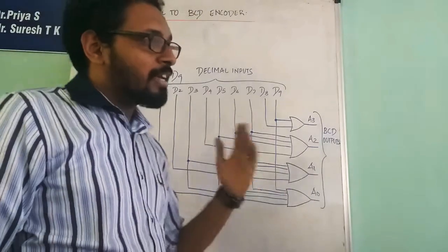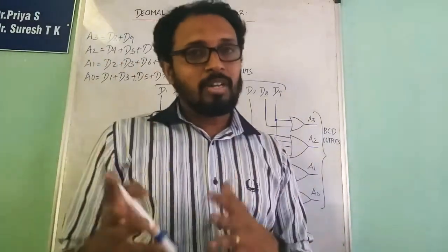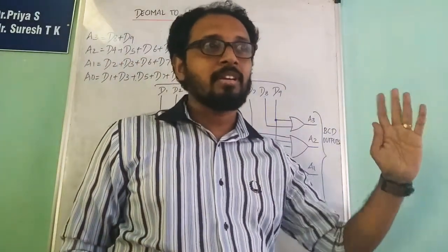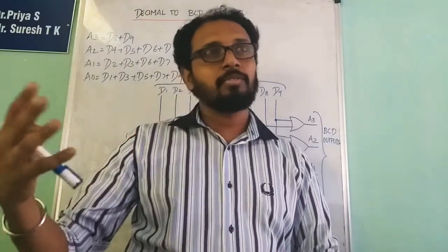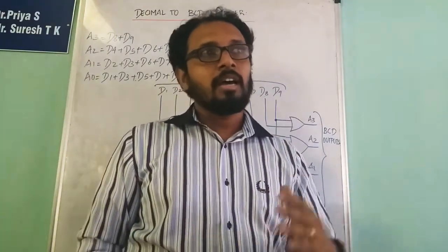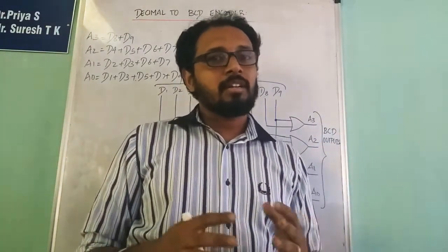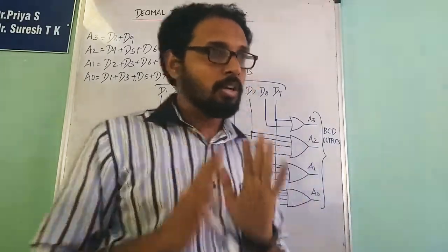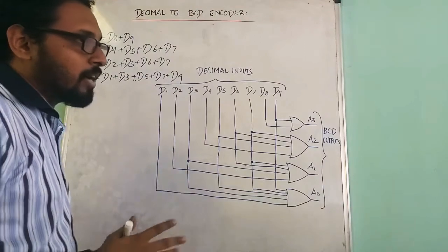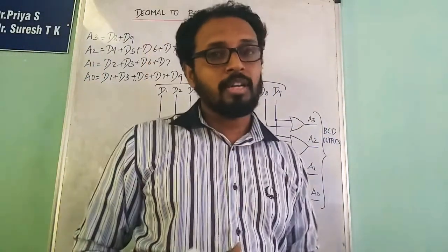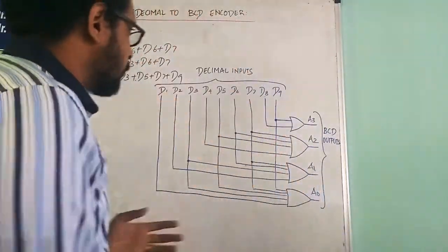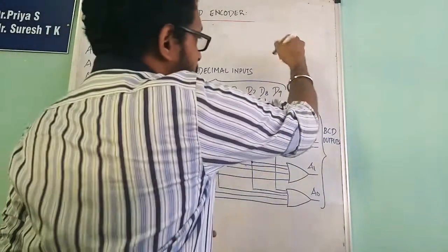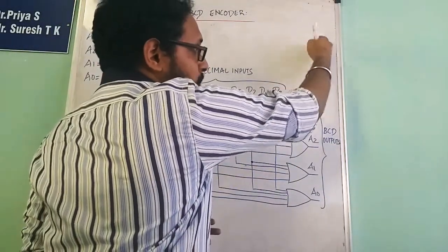In the case of BCD we can't exactly say that it's a don't care, because in the topics to come we will understand that the invalid conditions are considered as don't cares in the case of BCD. But for the time being, what you need to understand is D0 had no explicit input case, so we just ignore it, because the output we obtained was 0, 0, 0, 0.